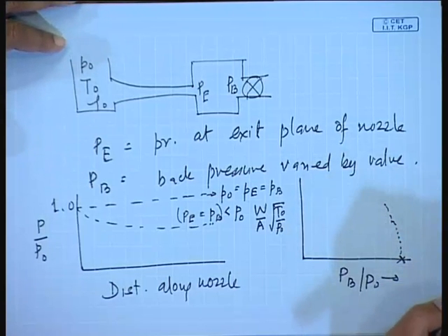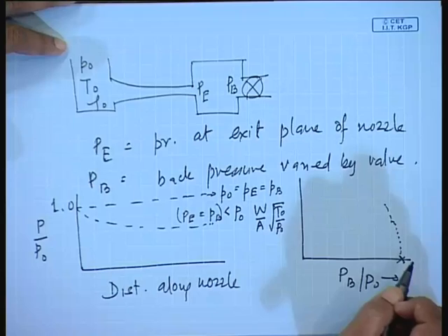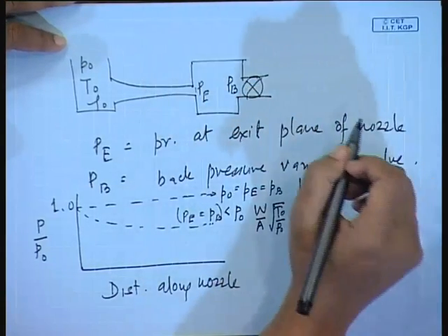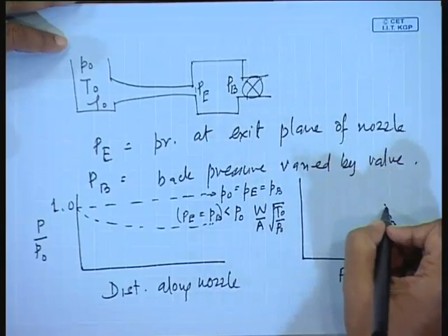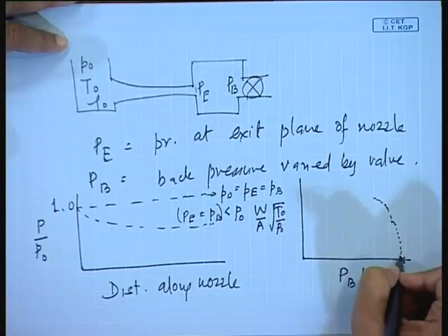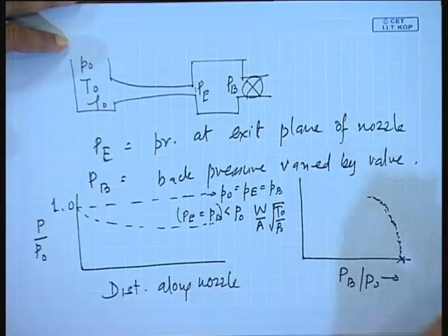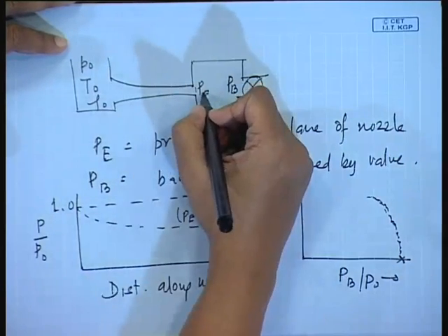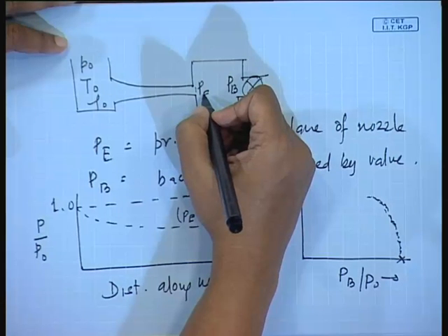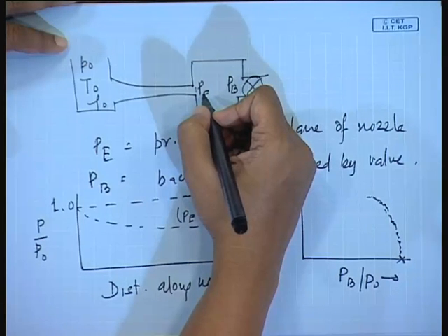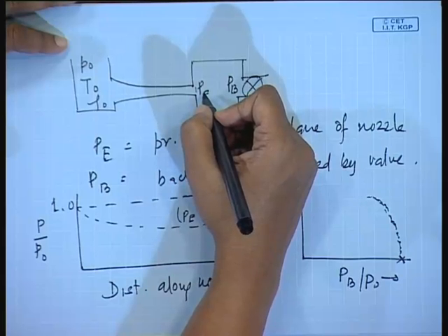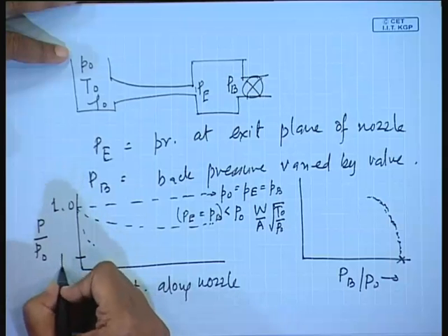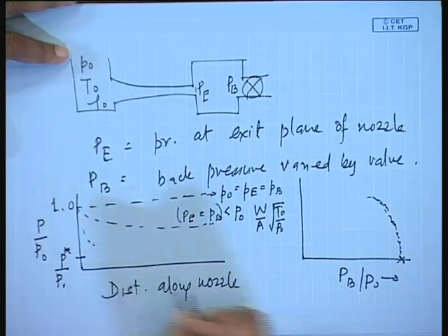in this particular way. Now, this continues till we obtain choked flow conditions here. When we keep on reducing the pressure, we find that the flow rate keeps on increasing. So, this goes on till the pressure here is under choked flow. Choked flow means we denote the properties by means of asterisks. So, therefore, this continues till we get P star by P0.